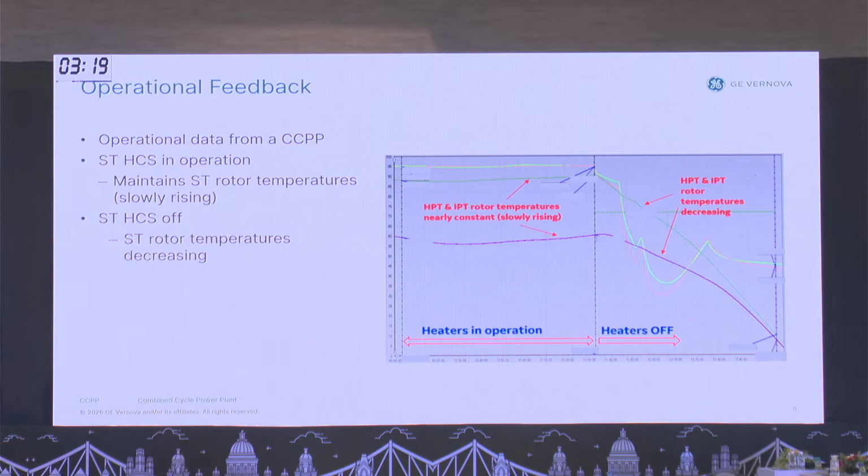And when we are using this heat conservation system on a long-term basis, if the turbine is at standstill maybe for 10 days, 15 days, then this hot air is actually reducing the moisture in the steam turbine. And since we are injecting dry air, the corrosion due to condensation is also reduced by this heat conservation system. So it is a kind of preservation as well for the steam turbine and all the rotating parts.